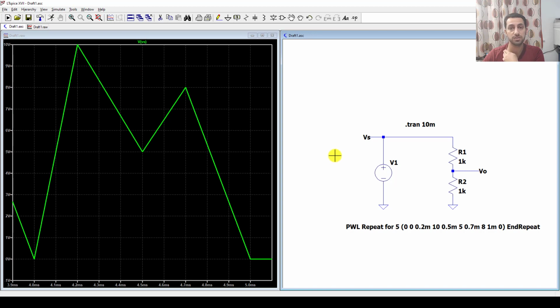Okay, now the last point is to do an AC signal, and I'm going to replace this resistor by a coil or inductor. And now I will make an AC analysis. What we mean by AC analysis is that we make the generator or power supply here an AC signal. That AC signal sweeps the frequency from an initial value to a final value, and it draws for us the frequency response, which is something like a Bode plot. So now let's do that.